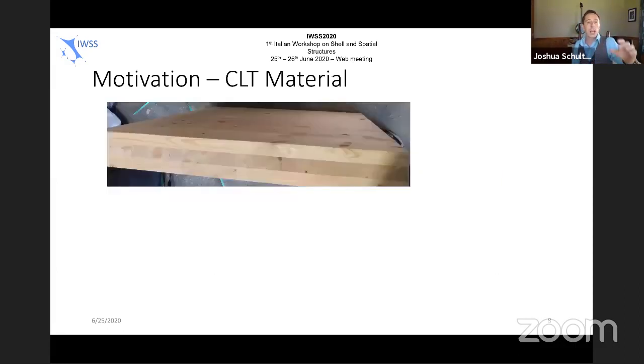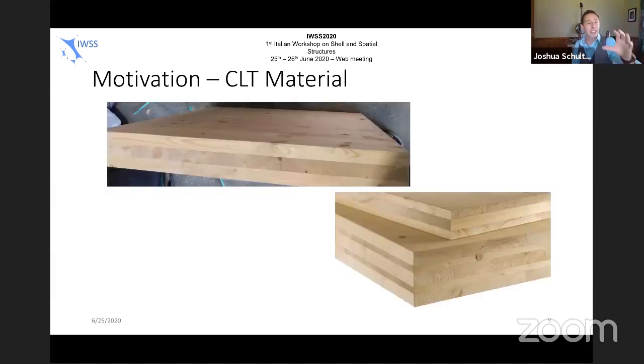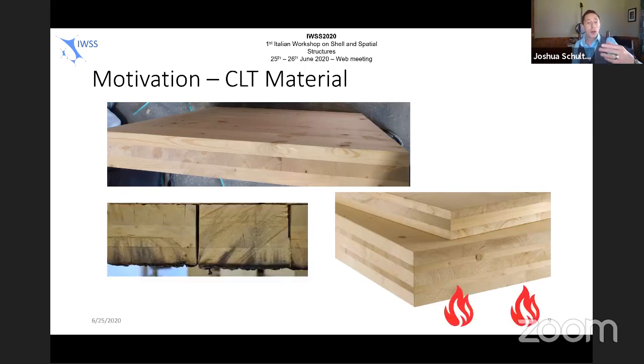And so the way we design these wood products, of course, is that mass timber is remarkably resilient to fire. But the way we deal with that is that as fire is introduced, you end up charring those bottom layers. Just intuitively, if you end up charring your longitudinal layers, even if you don't burn into that second layer, it is a transverse layer. So effectively when you introduce a 2-hour fire rating to a CLT material, you move from a 5-ply to a 3-ply.